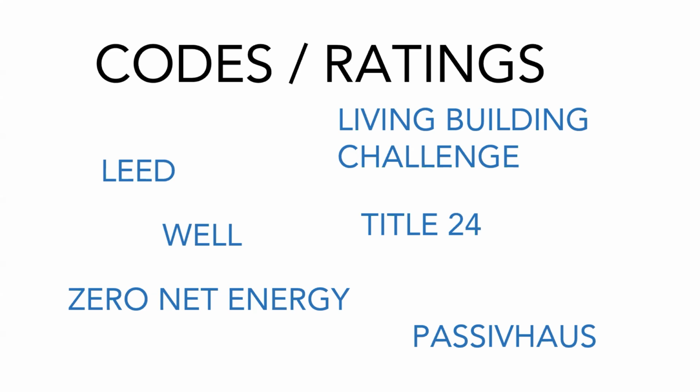Usually that is achieved through low EUI and renewable energy. And then there is Passive House, which looks thoroughly at the building envelope. Airtight and highly insulated envelopes are required for this rating. Title 24 is part of California's building code, and it is part 6 of the energy efficiency standards. Buildings must comply in California, and it's an effort to raise the minimum energy efficiency in California.